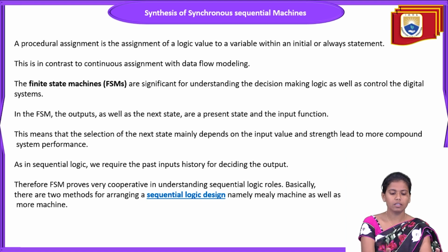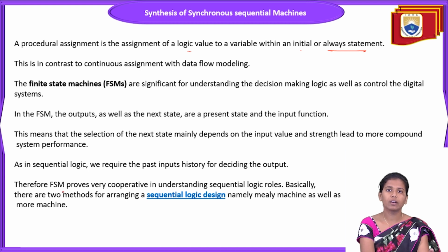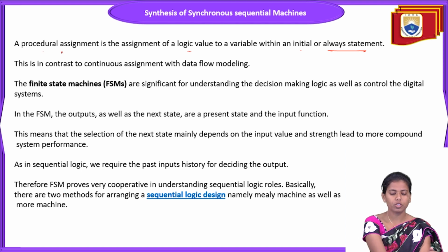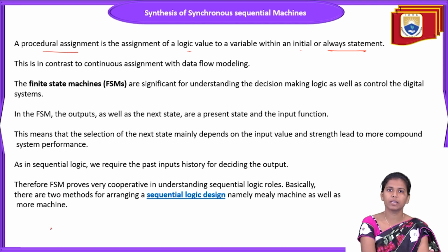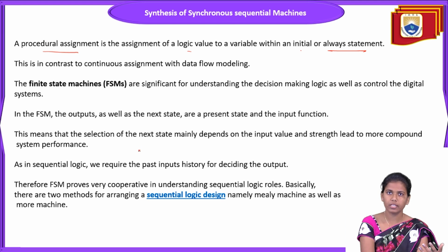The procedural assignment is the assignment of a logic value to a variable within an initial or always statement. As we are discussing the different statements in Verilog and VHDL, we have discussed the procedural assignment statements. They consist of blocking and non-blocking statements as well. If you are writing your code in terms of procedural assignments, you have to remember that your code should contain the always or initial statements. The procedural statement should be contained within the initial or always statement.